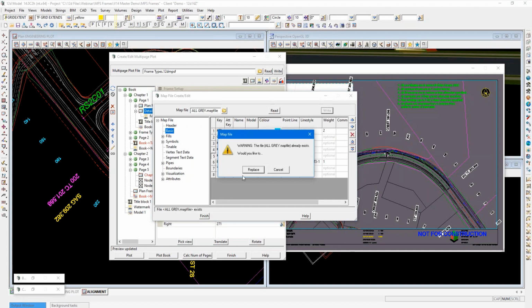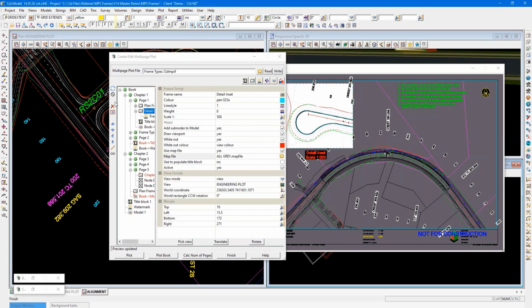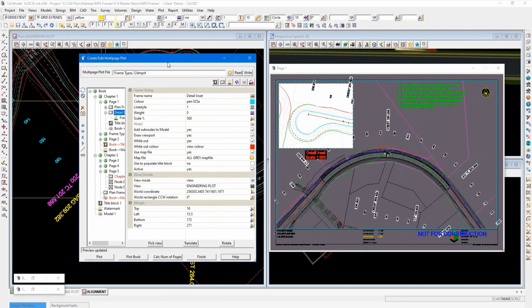So if I write that, place it, finish it, and just re-preview that, you'll see those little black lines will actually disappear around that cyan line. So that was my bad. Sorry, I was thinking about that later on as I was going through. So yeah, they need to be view color instead of no color to mask out or turn off those strings. So was there any other questions, Lisa?